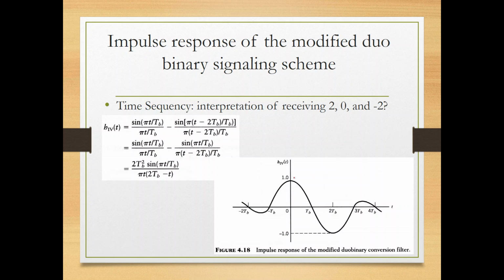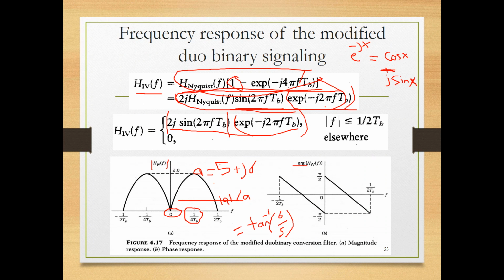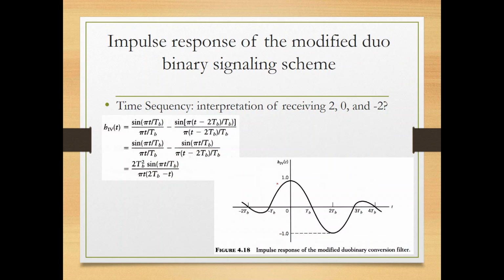Now, I found that this is the frequency response, yes, in amplitude and phase. I want now to find the time response. What's the time response? How do you find the time response? If I just ask you the question directly in the exam, how to find the time response from the frequency response, you tell me it's the inverse Fourier transform.